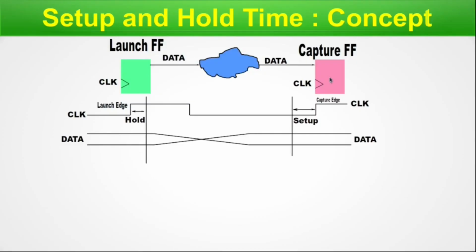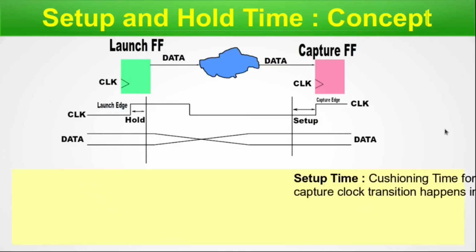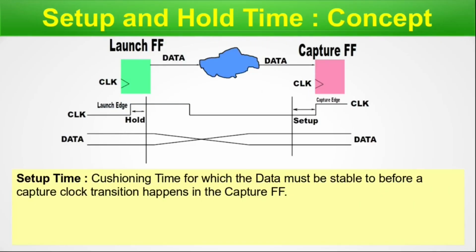Below, there is a timing diagram to visualize the data and clock transition side by side. In this diagram, we have the clock here and we have the data transition. If you look carefully, we have placed the hold and setup markers nearest to the respective flip-flop in the definition. Setup time: this is the cushioning time for which the data must be stable before a capture clock transition happens